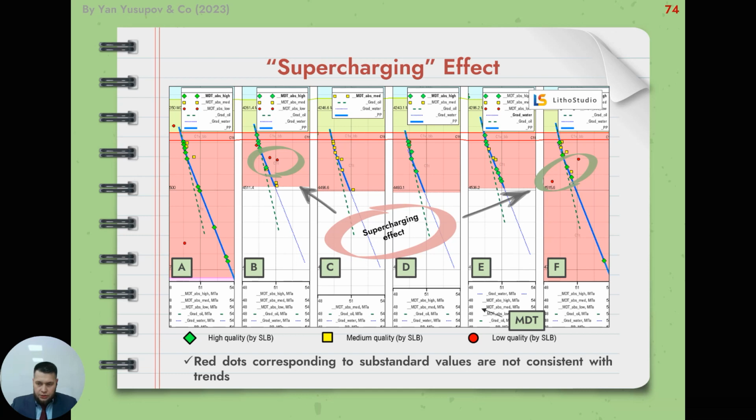Thus, the measurement taken by the formation tester will not reflect the actual pore pressure, since there is a pressure difference between the pressure on the surface of the mud cake and the pressure in the area of the formation not affected by drilling.